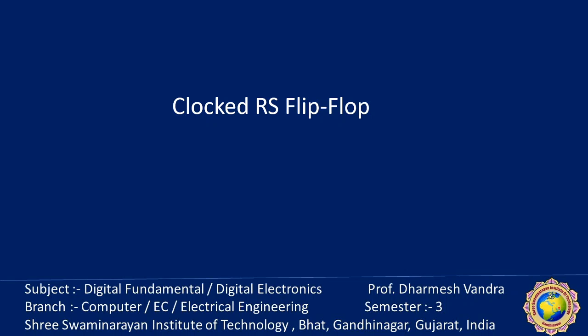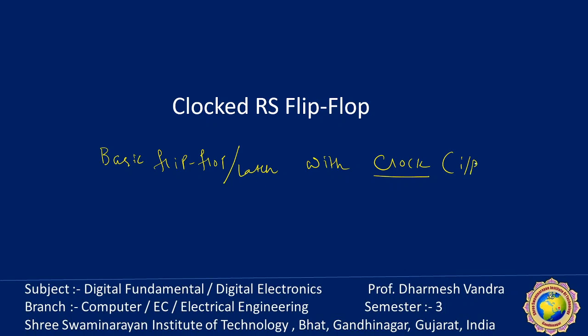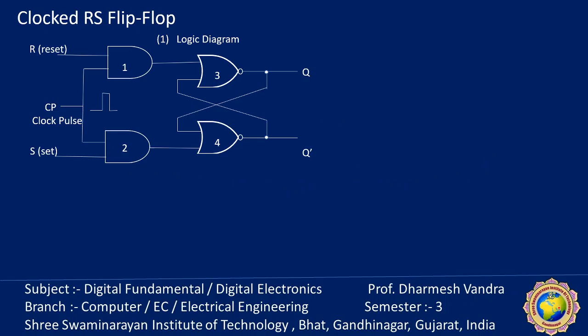So remember that the basic flip-flop or latch, with a clock. Some books say that if there is a clock input, this latch is called a flip-flop. Okay, and that is the clocked flip-flop. So the clocked RS flip-flop looks like this figure.